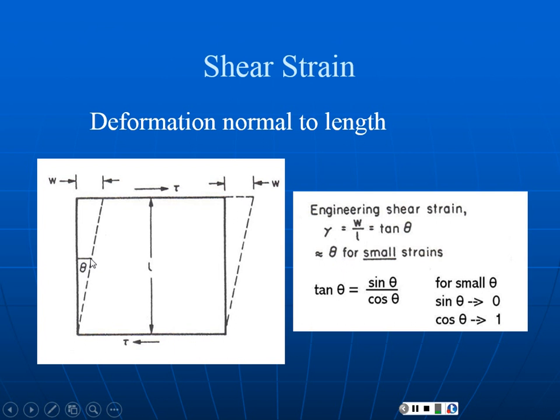Basically what we end up saying then is gamma is approximately equal to the angle swept out in strain. Now, that's kind of academic interest, except that you may be reading along in some paper or handbook, and they'll say, we measured a strain of 0.06 radians. And you say, what's that? Oh, okay, the radian's a magic unit. They're reminding me that this strain measurement was shear, not normal strain. So if you see radians, it's a shear strain that we're talking about.